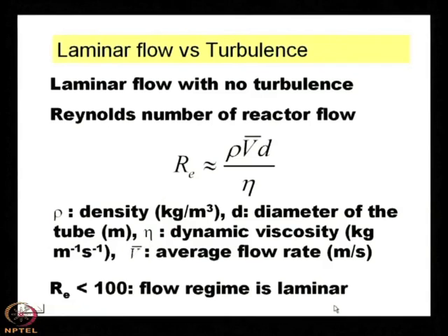Okay. So, there are two considerations, one is the Reynolds number to make the flow laminar, free from turbulence, and another we shall introduce the Rayleigh number, which will give you the diffusion, not the convection. The flow must be laminar, and also inside the reactor it will be diffusion, not the convection.